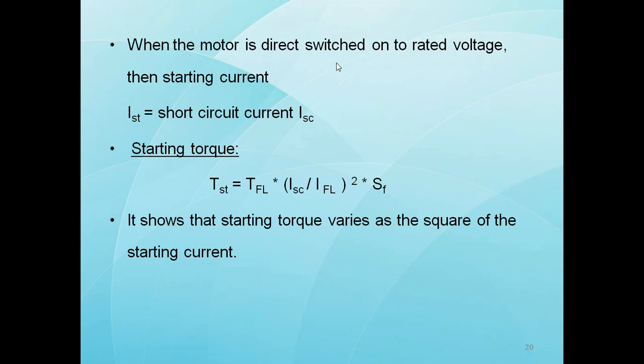The current drawn by the motor when started direct online is shown. Suppose we are using a push button type direct online starter. It is simple, inexpensive, and easy to install and maintain. These are the advantages of the DOL starter. Note on this torque equation.